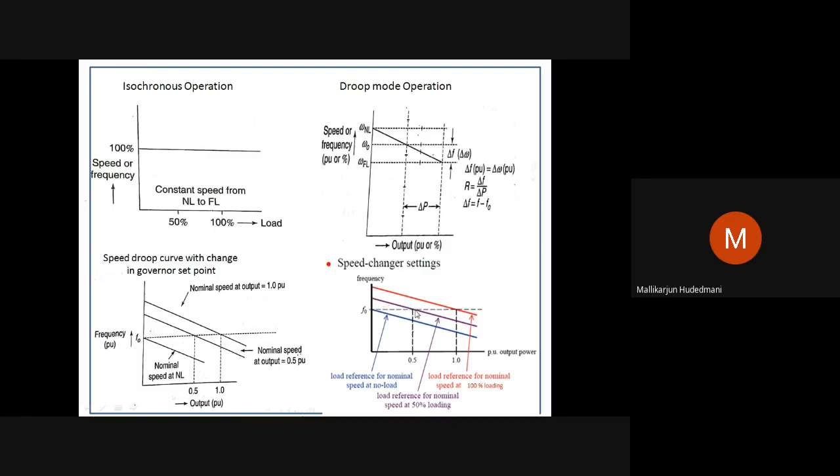Further, on this line only I need not keep operating without correcting the governor. If I increase the load it will ride forward, but the frequency will be noticed different. Then to obtain 100% output with the base frequency constant, this line has to be shifted forward. Again, input increment has to happen. This is what this curve says. Droop curves keep correcting. The subsequent drop of frequency or RPM is corrected by relevant opening up of valves at the controller, so that mechanical input will shift the RPM and frequency back to requirement.